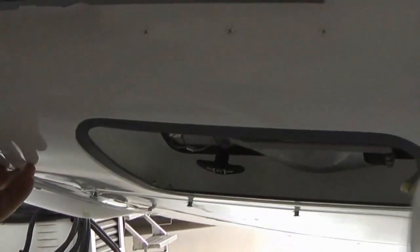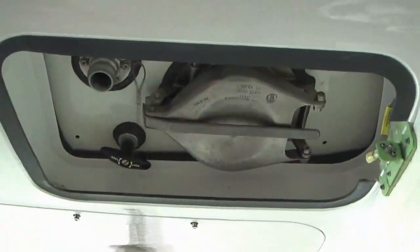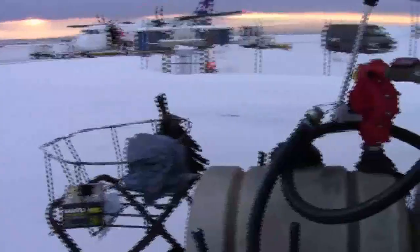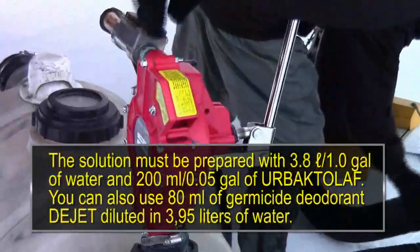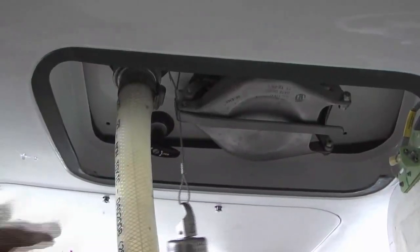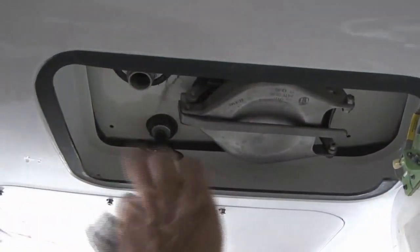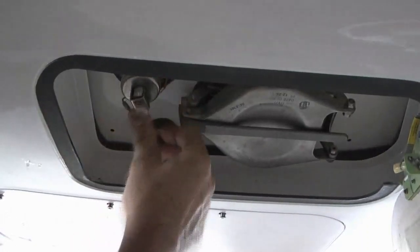Open the access panel. Remove the rinse nipple cap from the RTS rinse valve. Connect the lavatory filling coupling to the RTS rinse valve and fill the waste system with the solution prepared in the lavatory servicing cart. After filling the waste tank with the solution, disconnect the lavatory filling coupling from the RTS rinse valve. Install the rinse nipple cap on the RTS rinse valve. Close the access panel.